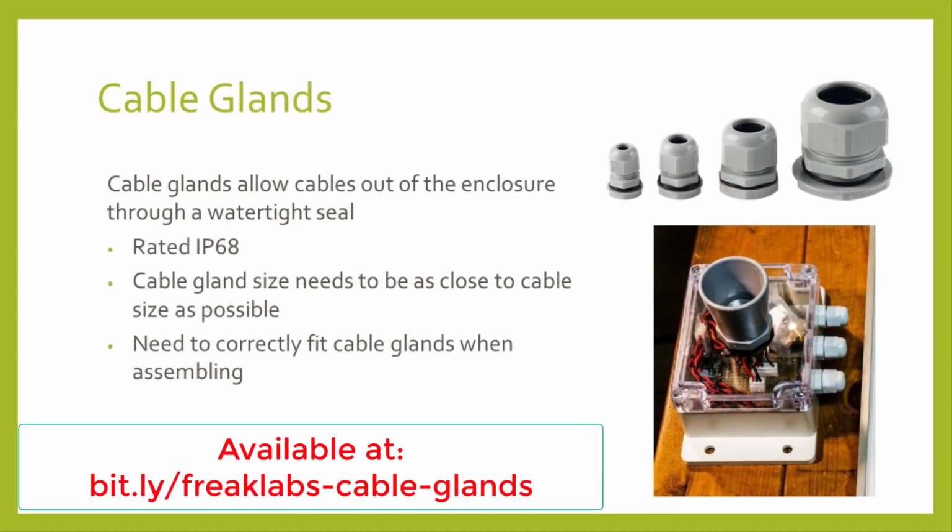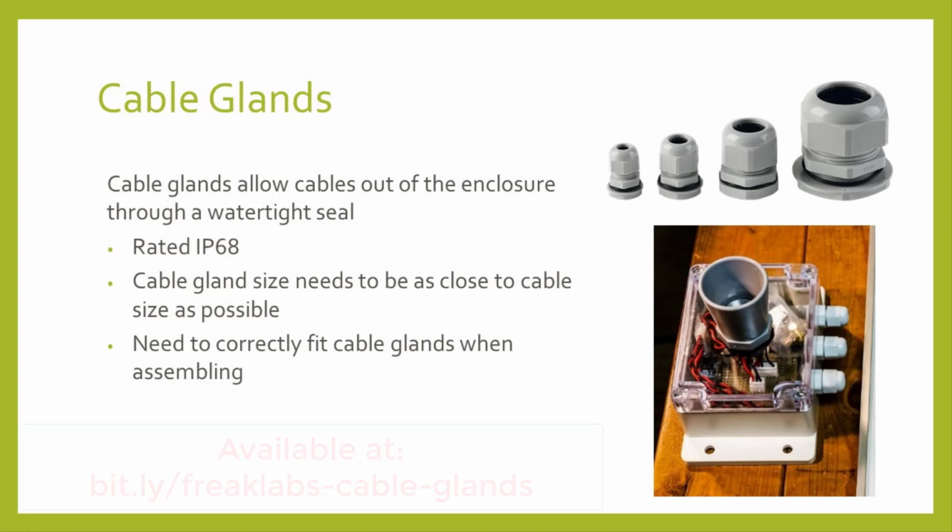A cable gland allows us to create a watertight hole in the enclosure through which we can thread cables. Cable glands are rated at IP68, which means they're submersible. However, it's important to match the size of the cable gland to the size of the cables as much as possible and have them correctly fitted. Also, if you plan on having the cable gland submerged in water, we recommend testing it first with the cable that will be used to guarantee that no water will leak through the system.